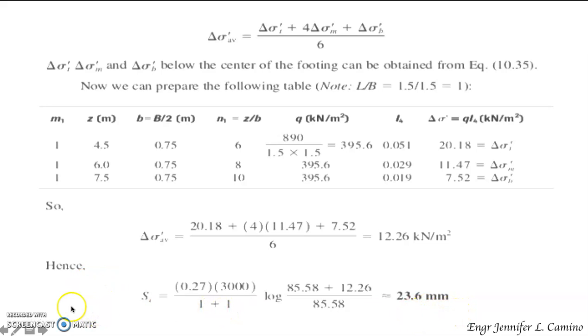That ends our discussion for compressibility of soil. When we talk about compressibility of soil, we're talking about the decrease in volume of the soil due to the application of mechanical loading. If you compress saturated soil, that is termed consolidation. We have identified the different consolidation settlements: elastic or immediate, and the primary and secondary consolidation settlement. So thank you.